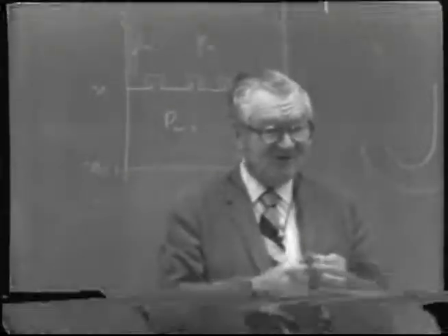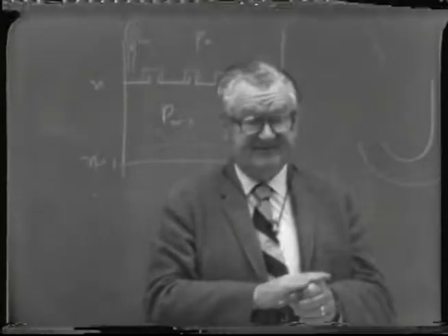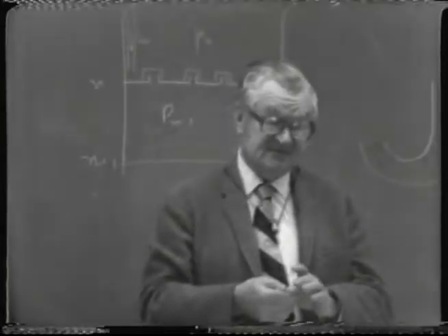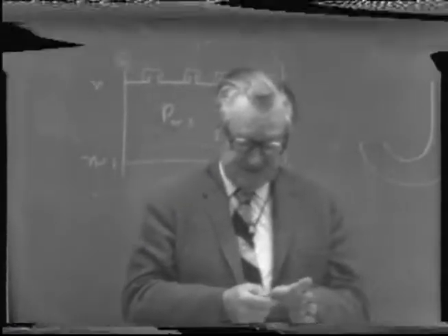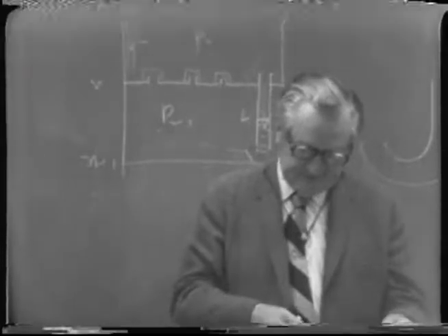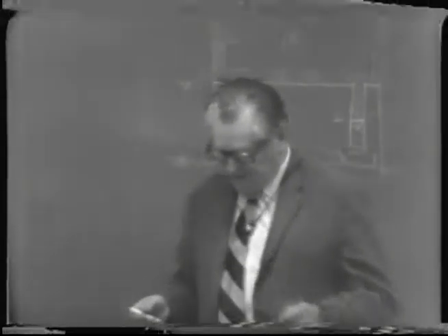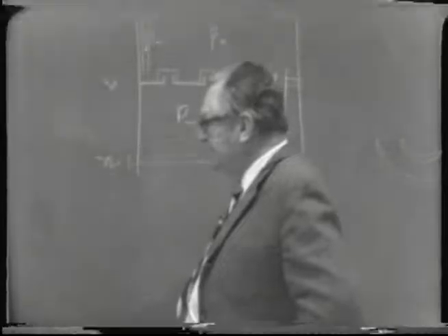If you have small enough holes, water, which has a high surface tension, and particularly if it doesn't wet the plate very well, won't run through very well. But something with a lot lower surface tension will run through small holes. So the size of the hole is somewhat important, and has to be calculated or estimated in terms of the surface tension of the fluid to be handled.